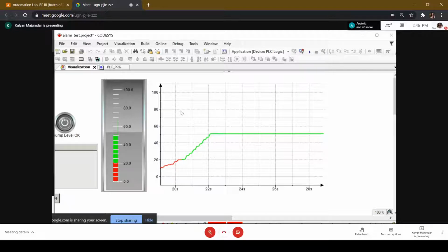The main reason why you have a closed circuit television is that all the data collected from the cameras is actually stored within the hard disk. So this image feed is stored for a significant amount of time. For how long it is stored depends upon the capacity of your hard disk and, of course, upon the number of cameras that you've got. But the fact is, whatever image feed you have is stored in a hard disk. So in case of an abnormal situation, you can look back at what exactly happened at that particular point of time because you have stored this information within the hard disk.